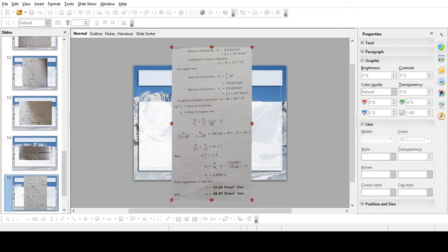So I am substituting the values. Sigma s by 2.1 into 10 to the power of 5, which is the modulus of elasticity of steel, plus sigma c by 1.1 into 10 to the power of 5, the modulus of elasticity of copper, should be equal to T, the change in temperature, that is 190 degrees, into alpha c, 18 into 10 to the power of minus 6, minus alpha s, 11 into 10 to the power of minus 6.